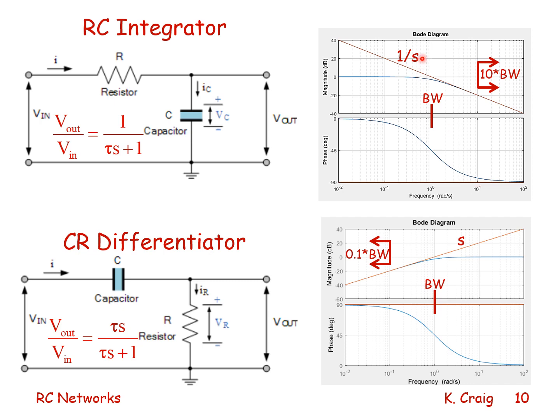Now, S is the same as D, the differential operator. D, or S, means take the derivative. 1 over D, or 1 over S, means take the integral. So if I look at the frequency response of a pure integrator, it's given by this straight line here.